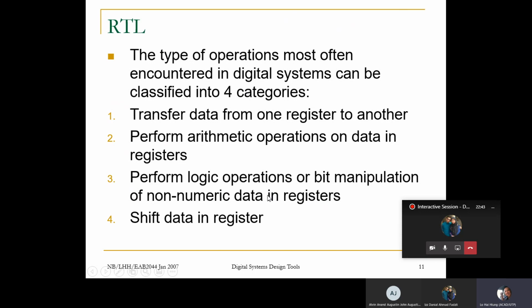The easy, quick rule of thumb is that a logical operation produces a 1-bit output, because logical operations are only interested in true or false. To know true or false, we only need 1 bit, with 1 as true and 0 as false. In a bitwise operation, we do the logic operation at every bit. So bitwise operations can produce multiple bits. That is one of the fundamental differences. If you keep that in mind, it should help you avoid a lot of errors in writing hardware.